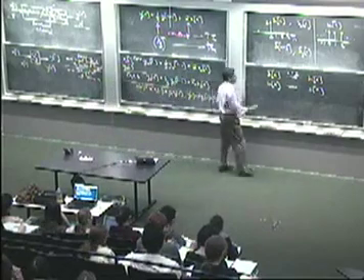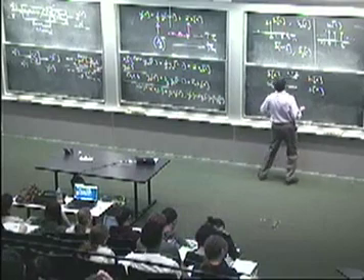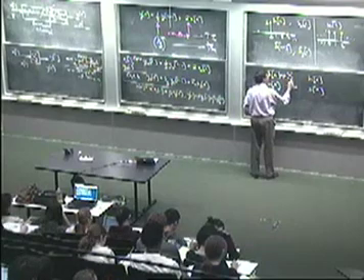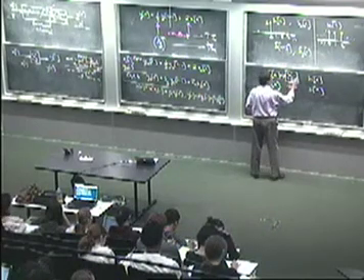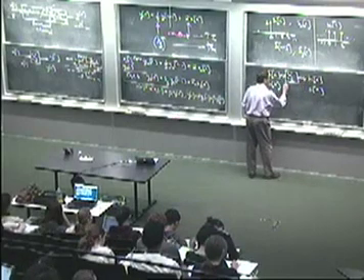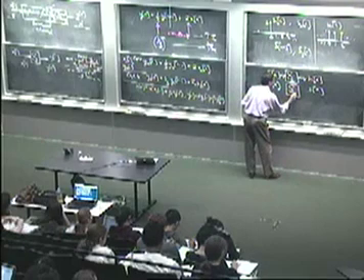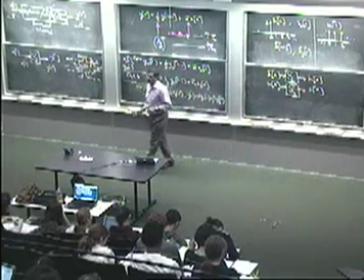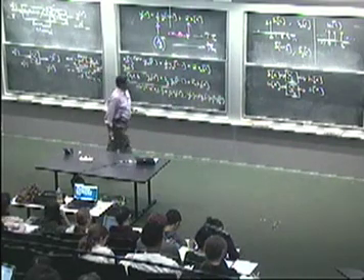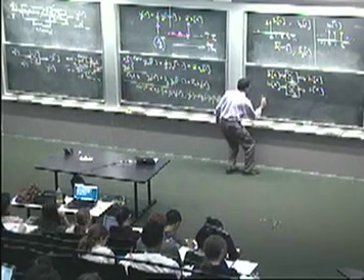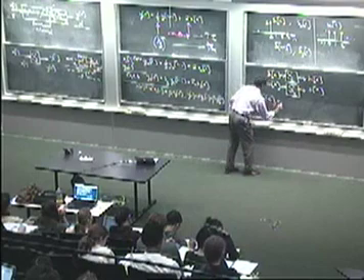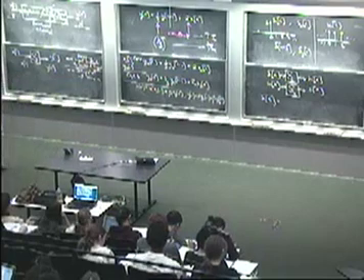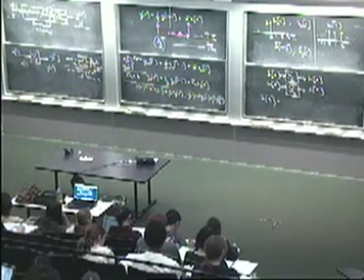So here's one way to think of that. This, by the way, is the same LTI system. Maybe I should indicate that more explicitly by saying it's a specific system, system 0. And with the same system, I'm trying to deduce the results of another experiment. So if we're thinking superposition, can you tell me how to write the unit sample function as a linear combination of unit step functions, maybe delayed unit step functions, scaled unit step functions? Yeah?